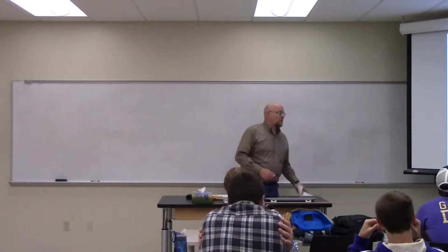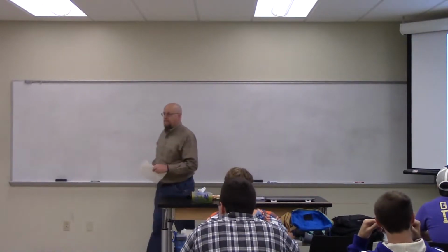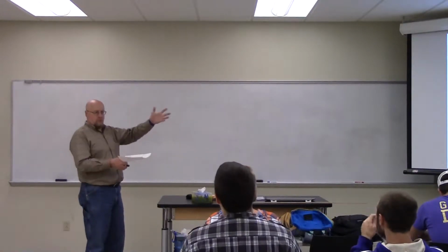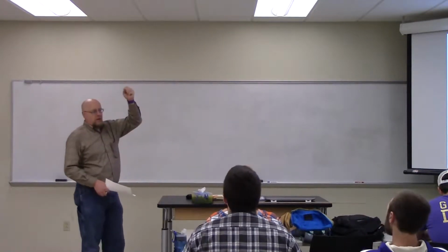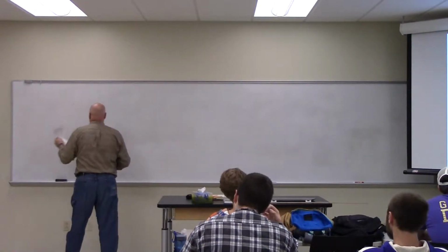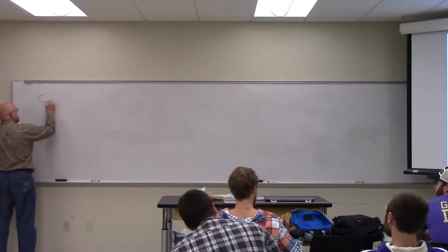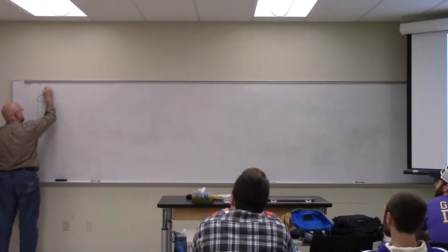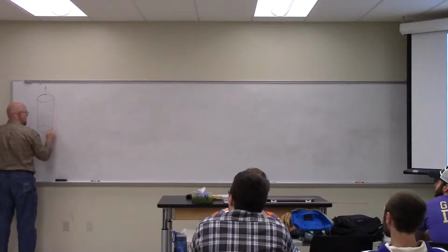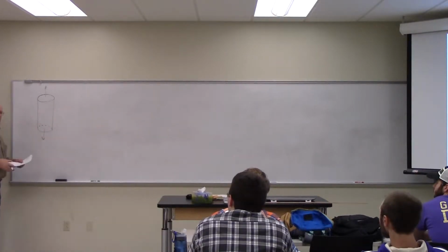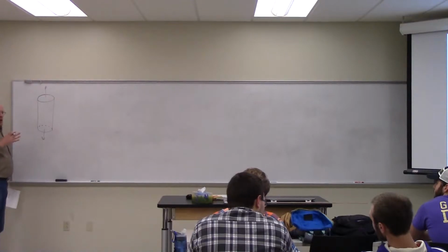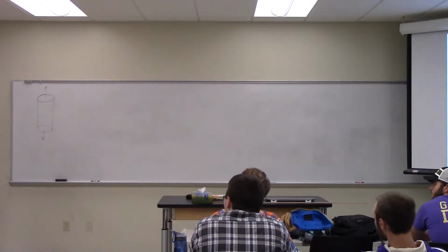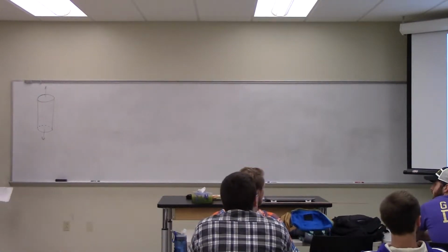Now what if we take this cell and actually apply a stress to it? We're going to take that FCC unit cell, actually take the whole crystal, but expressed as a stress on the unit cell, and we're pulling it in the 100 direction. So on a macroscopic scale, we have this tensile specimen, we're pulling it upward in the vertical direction, right? And we know that it wants to slip on that slip system we've talked about.